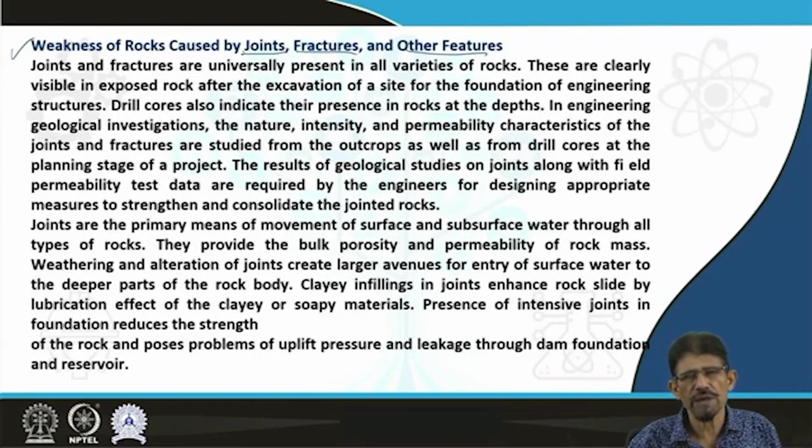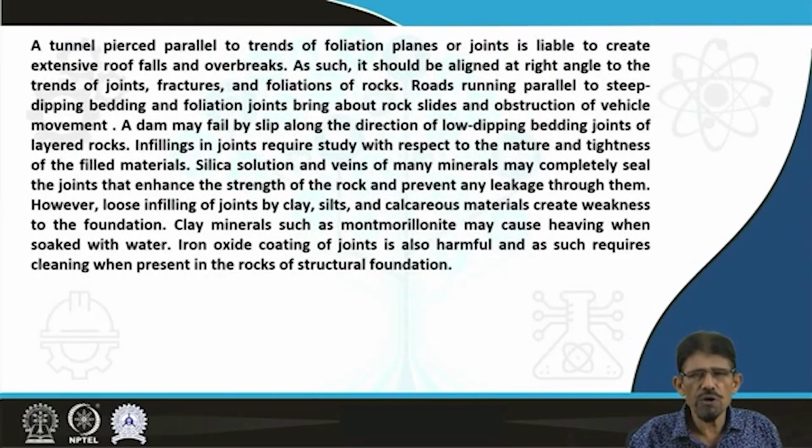mud cracks, sun cracks and others, which directly or indirectly influence the strata lying below the dam, below the road pavement, below the track of railroad and below the dam foundation, below the building in general. Similar to surface structures, underground structures also face a lot of problems due to the presence of foliation, lineations, fractures, joints, etc. that result in overbreak and require a lot of precautions regarding the support system to provide suitable support and stabilize the excavated opening.